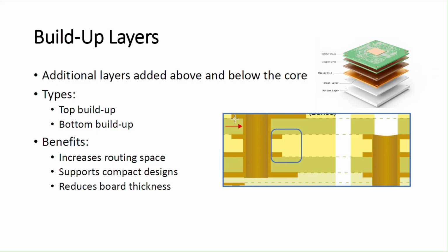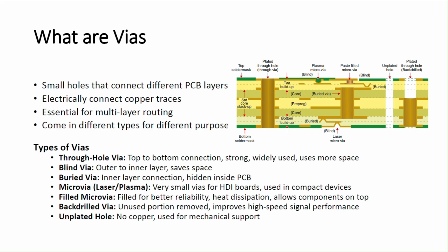The 5 volt may be coming from this side, so 5 volt is entering. This 5 volt goes directly to the top layer. Now you want to tap the same 5 volt to the internal layers, then this 5 volt will appear in the internal layers through this wire. So these vias are a kind of conductive path to the internal copper layers, and this will help you to electrically connect.